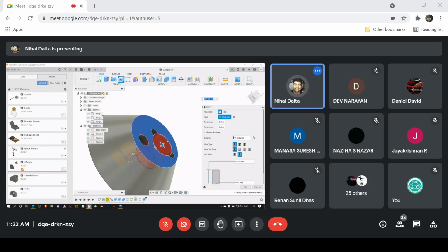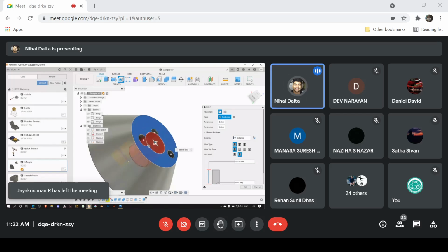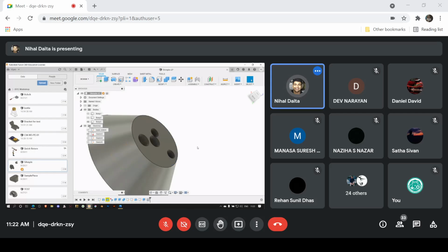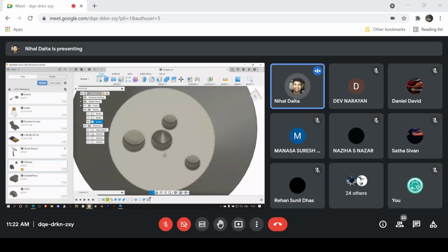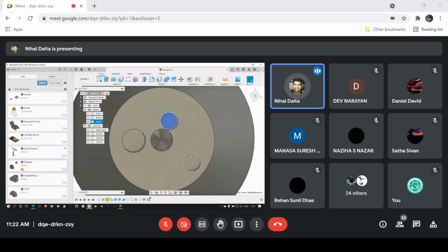I guess you can just click on the surface and you can move this, right? It snaps to the points as well. So like I mentioned yesterday, you can use a separate sketch with some points if you want to mark the points out first. You just place it there and it snaps there, as you can see. Let me just reduce the radius, and if I click OK, it's not that clear, but these are all flat bottom holes, right?